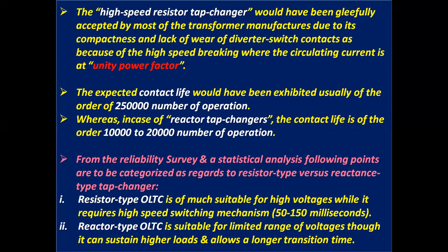The expected contact life usually is of the order of 25,000 operations, whereas in the case of reactor tap changers, the contact life is of the order of 10,000 to 20,000 operations.